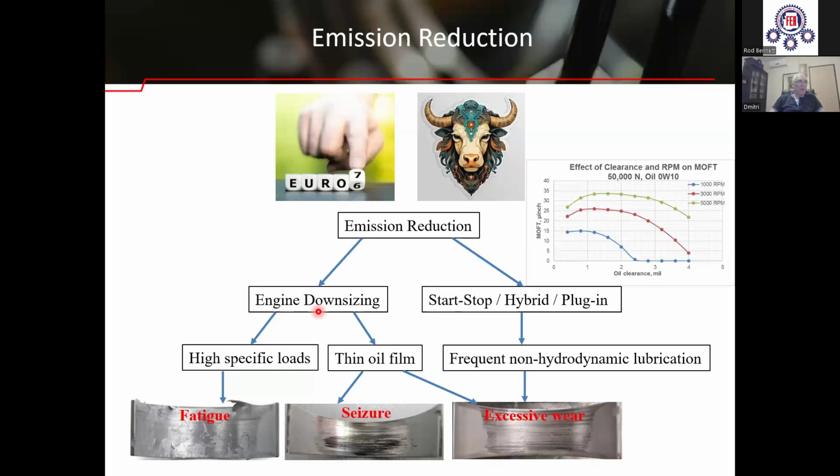The crankshafts are shorter and they have lower diameters. In the shorter crankshafts, the spaces for the bearings are also shorter. The bearing diameters are also smaller. So the combustion pressures, on the other hand, are increased because of the enhanced engine efficiency.